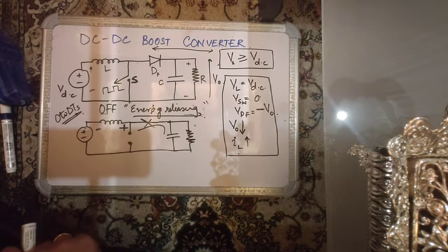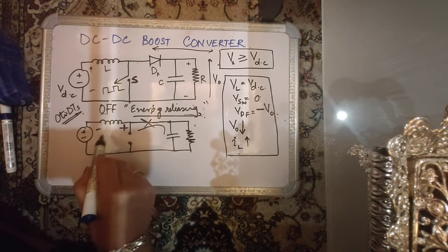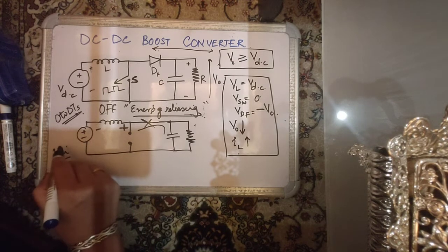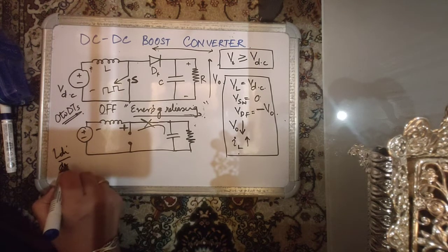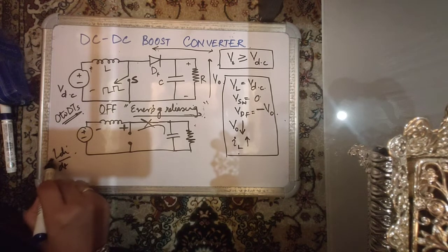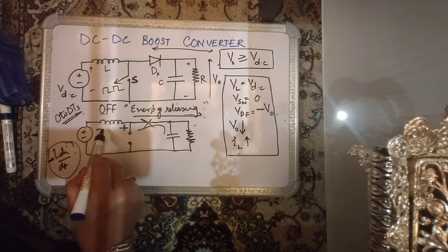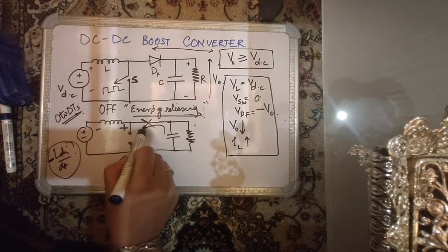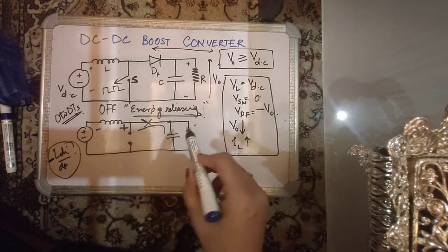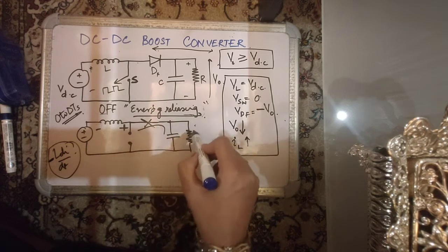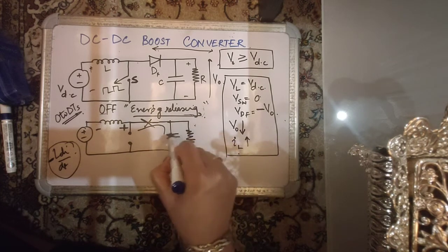Okay, so now due to this high magnitude L dI by dt kick, because you had interrupted current in a very small interval almost instantaneously and made that current apparently zero, a very high magnitude negative voltage spike is induced here because of a classic inductor behavior, which forward biases your freewheeling diode, and hence this inductor starts delivering energy that it had previously stored. It now starts delivering it into the load and into the capacitor.